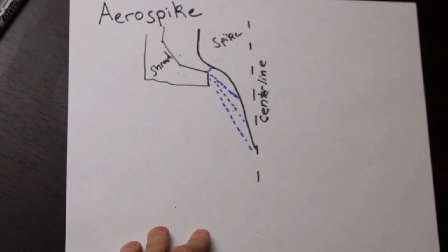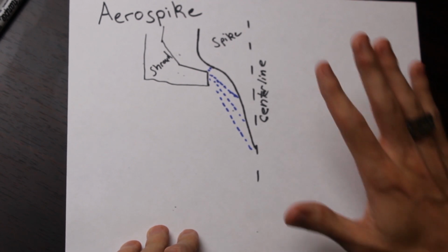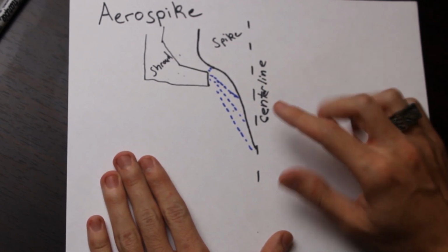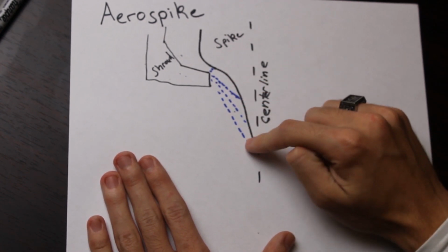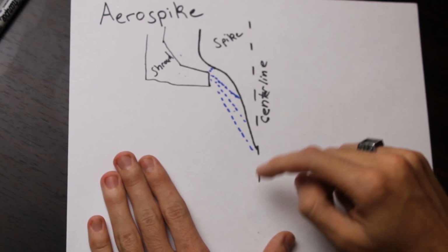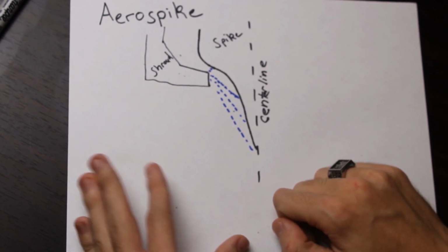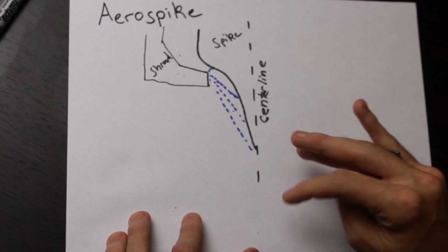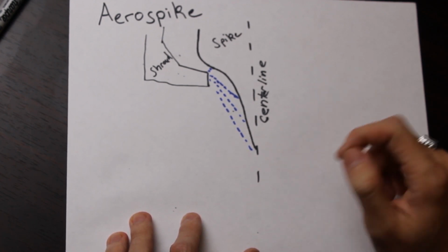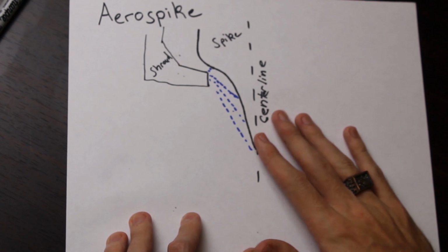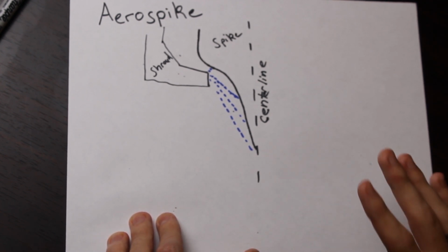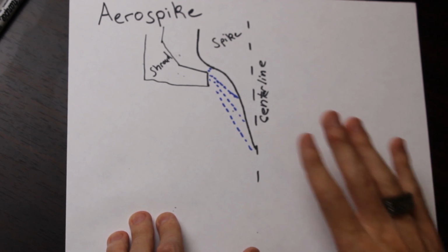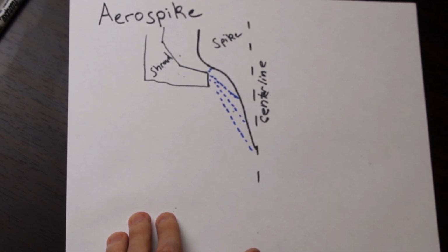So just to be somewhat rigorous about this, we kind of guesstimated what the spike is going to look like, and we're going to check all this here at the end. The center portion right here is the spike, and then this little lip right here is the shroud, and that's what makes the throat. This is a full-length toroidal aerospike. That means that it's radially symmetric, and the spike is not truncated at the end. It actually is easier to design a linear aerospike. You get to drop a couple of terms in the differential equations sooner. But just for giggles here, this is a toroidal aerospike. I already had all the math set up to do it.